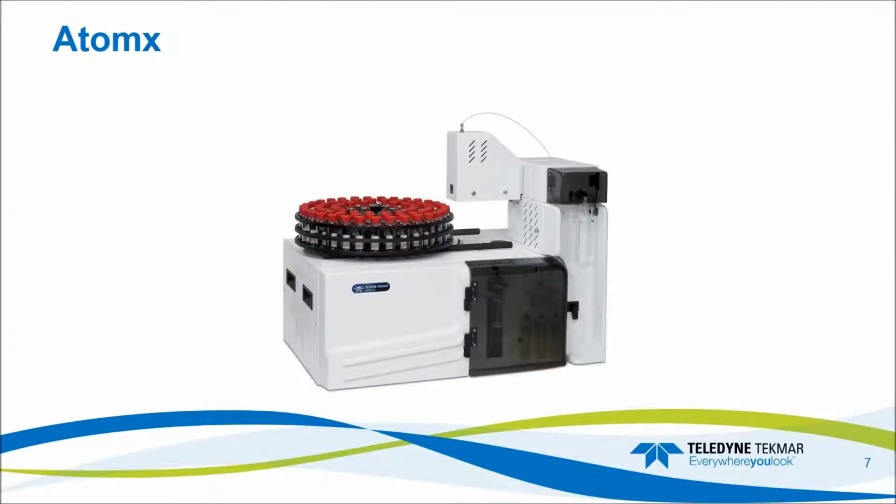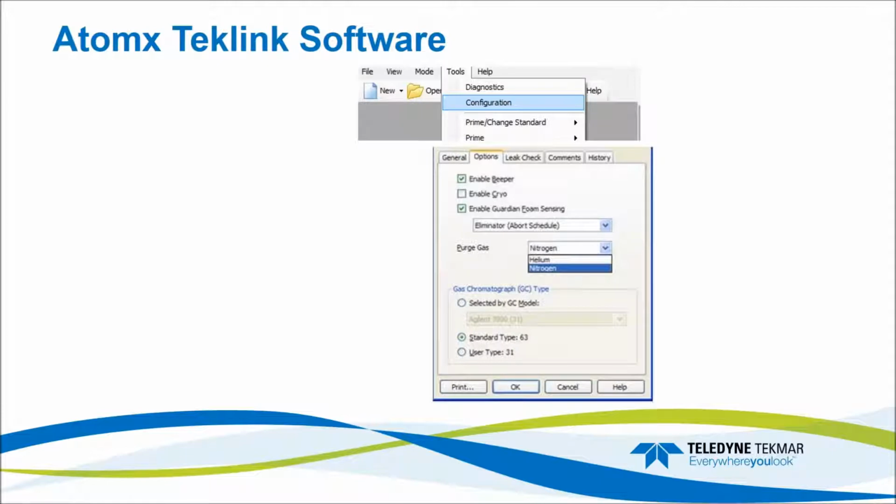Okay, so let's start with a couple examples looking at the Atomx, and then we'll move on to the Lumin and look at some water examples. Selecting your nitrogen purge gas in your Atomx Teklink software is very simple and straightforward. We go to Tools, Configuration, and then we choose the Options tab of the configuration window, and then we have our purge gas. It's simply a drop-down menu, and we can select helium or nitrogen.